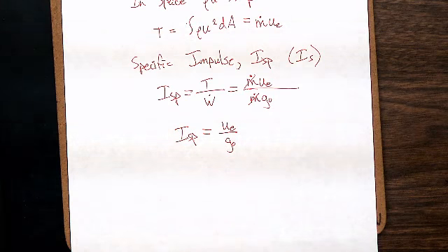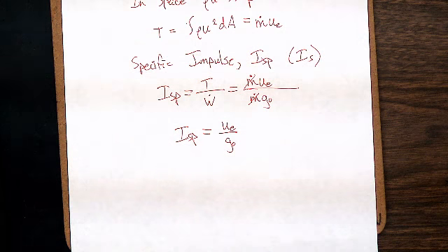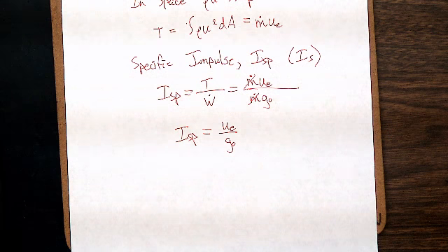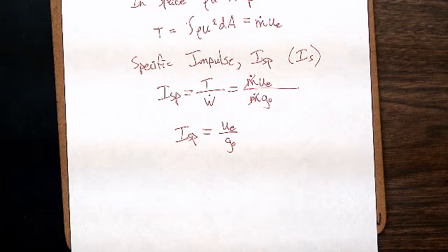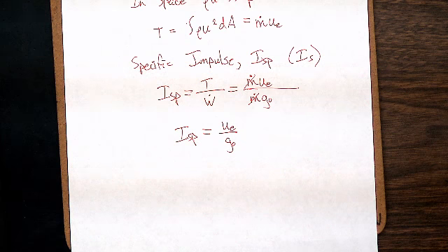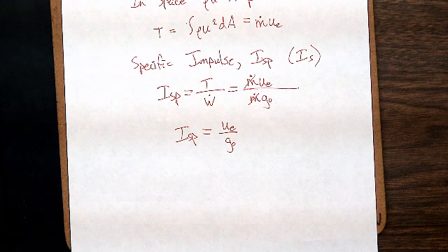And this is an easy thing to deal with in MKS units, because if you need to know an ISP, you know the exit velocity or vice versa with a factor of roughly 10, 9.8 meters per second squared.